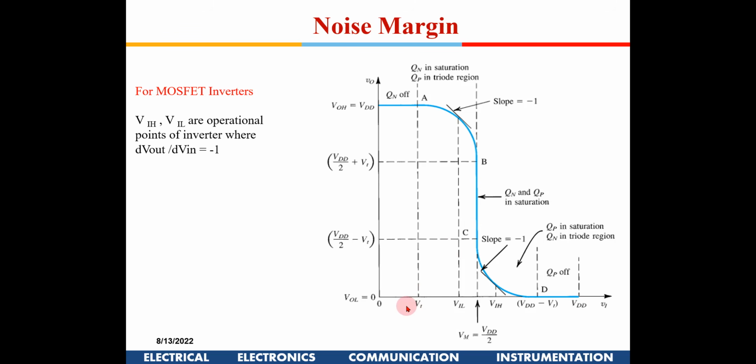The threshold of the gate of the MOSFET? Yeah, it will be. There will be threshold and the relative strength of the right, and we will derive these equations of the noise margin today. Okay, so we'll see it is a factor. The greater the threshold voltage, that much would be the better. Okay, so we'll derive those expressions today.